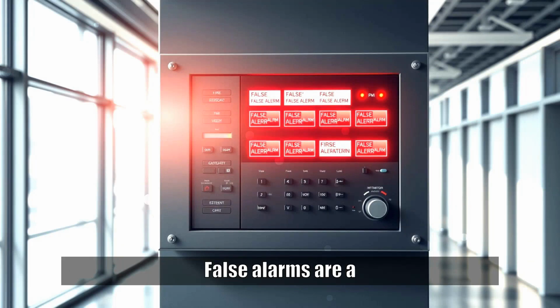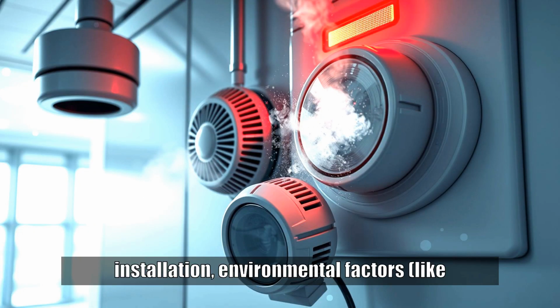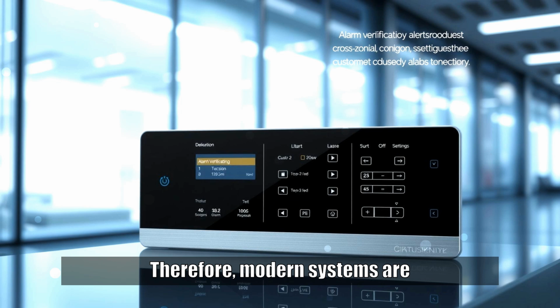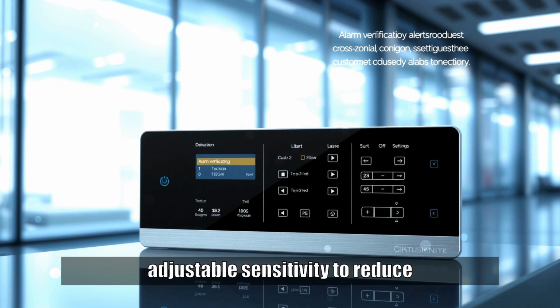False alarms are a major challenge for fire alarm systems. They can be caused by faulty detectors, poor installation, environmental factors like steam or dust, or even malicious tampering. Repeated false alarms lead to complacency among building occupants and can overwhelm emergency services. Therefore, modern systems are equipped with features like alarm verification, cross-zoning, and adjustable sensitivity to reduce false activations.